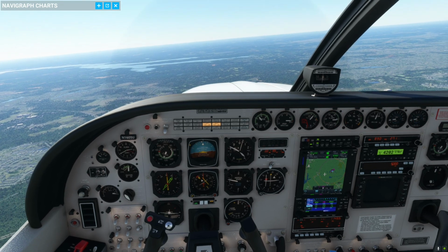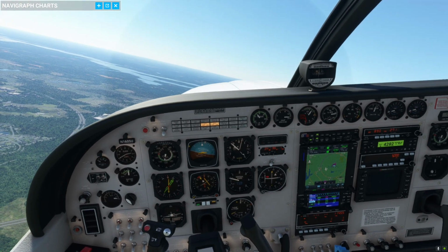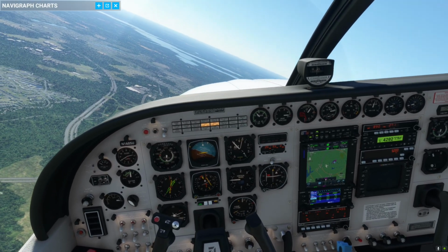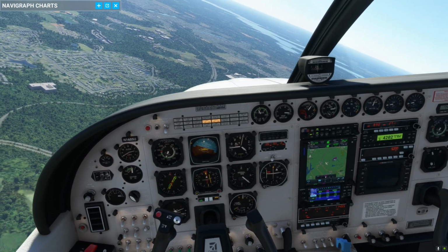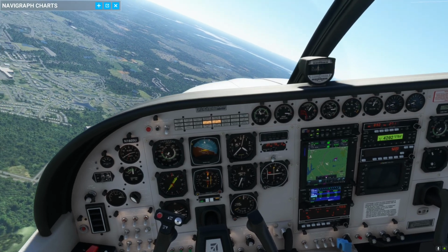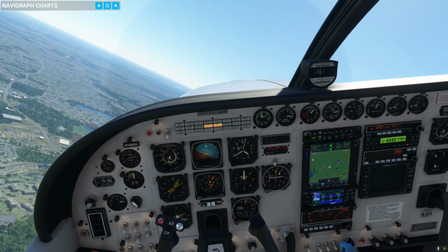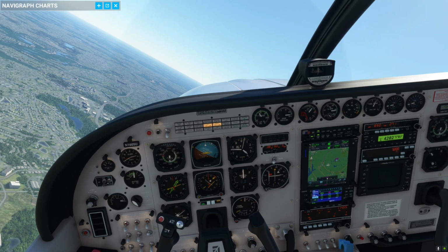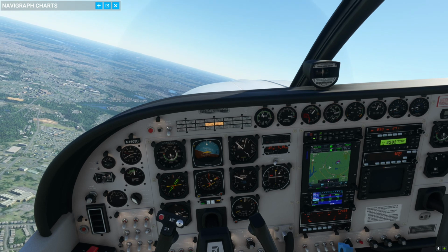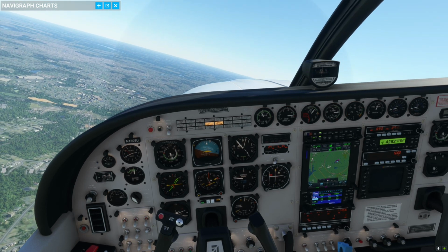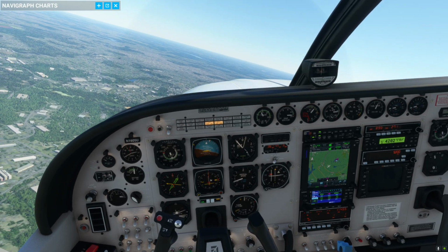There, left downwind. Okay, so we'll turn to the left. We'll do basically a 200-degree turn here, because the whole idea is we need to lose a little more altitude. We need to fly the reciprocal of our runway. Whoa. For a left pattern, that's going to cause me to overfly basically the...